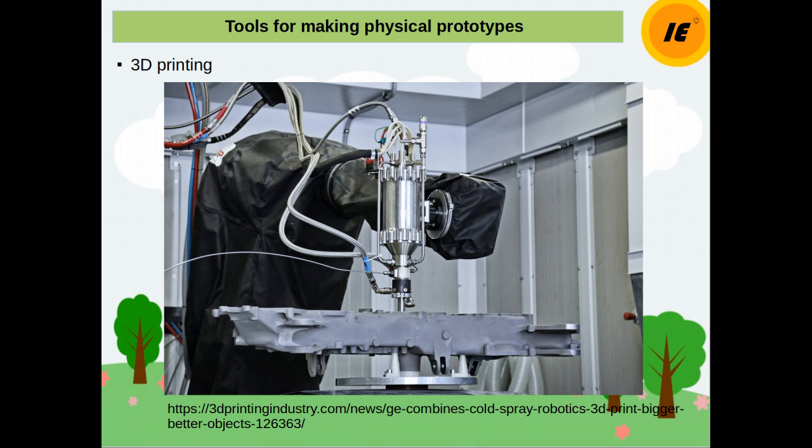Most of the technologies work by constructing an object one cross-sectional layer at a time, by depositing a material or by using a laser to selectively solidify a liquid or powder. The resulting parts are often made from plastics, but other materials are available, including wax, paper, ceramics, and metals. In some cases, the parts are used directly for visualization or in working prototypes. However, the parts are often used as patterns to make molds from which parts with particular material properties can then be molded or cast.